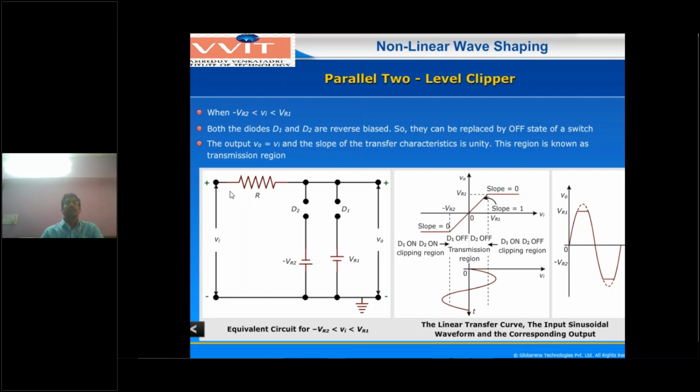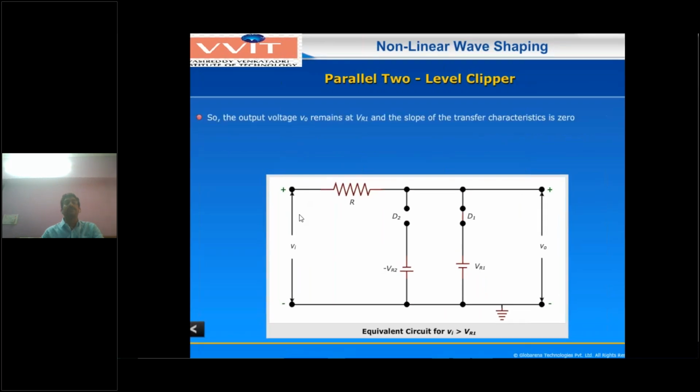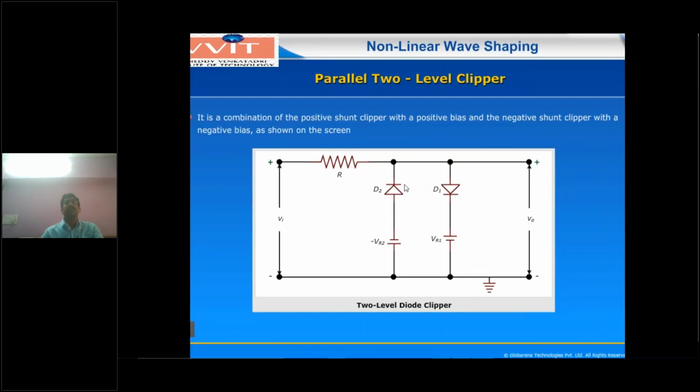First voltage. Now coming here, 2 volts is the direction. Now diode D2 is in reverse bias direction. Here will be 2 volts, so here will be minus 2 volts. Now this minus 2 means less voltage compared to the cathode. Anode is at less voltage, so diode D2 will be in off condition.